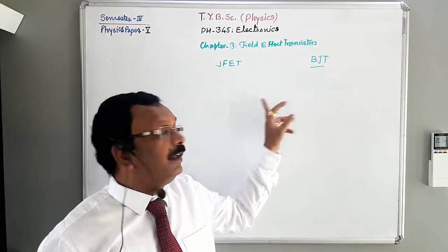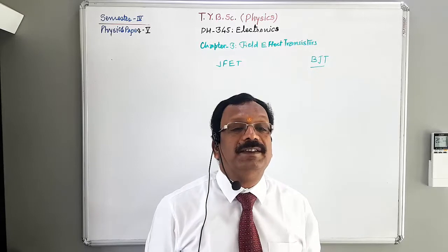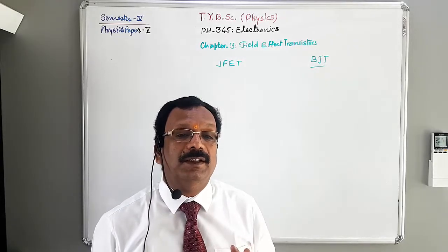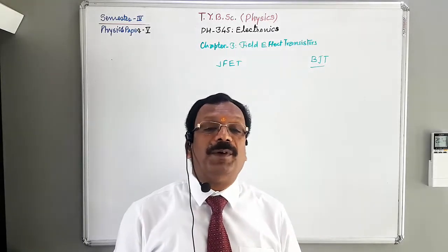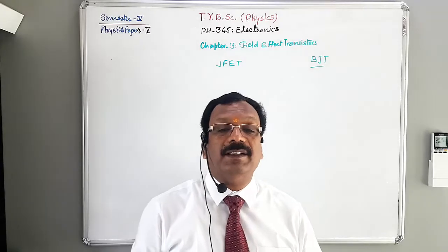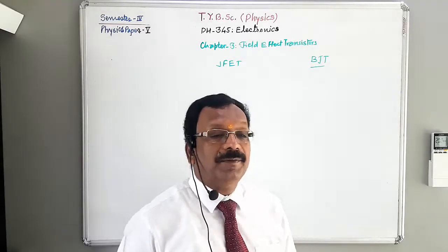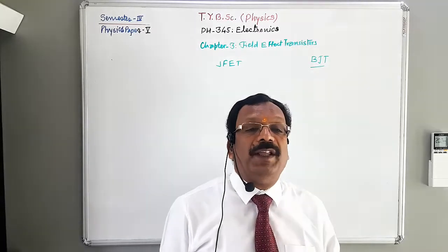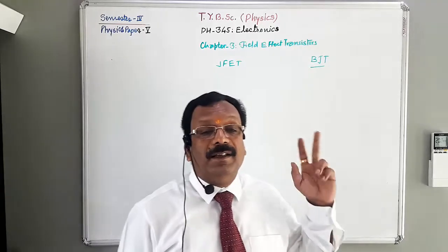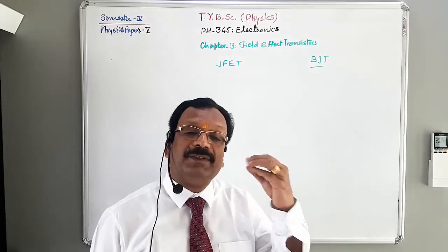resistance. Okay. Next one, FET has negative temperature coefficient of resistance at high current level and prevents thermal breakdown, whereas BJT has positive temperature coefficient of resistance at high current levels and does not prevent thermal breakdown. There is always thermal breakdown. That's why this FET is having very good thermal stability as compared to BJT, or we can say that BJT has lower thermal stability, or thermal stability of BJT is very poor.